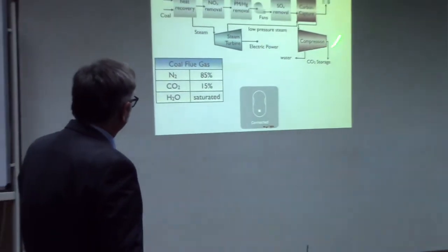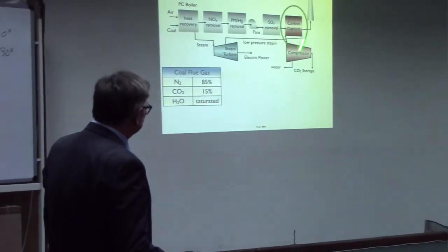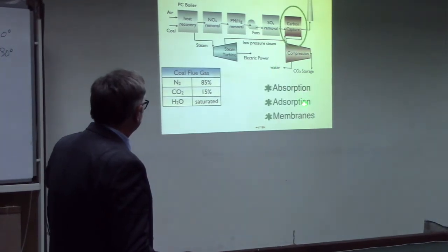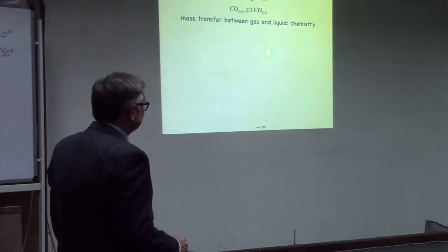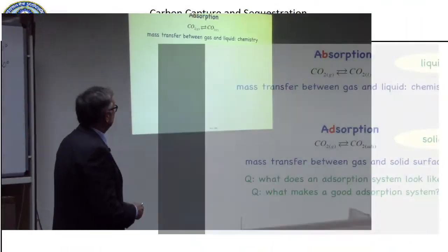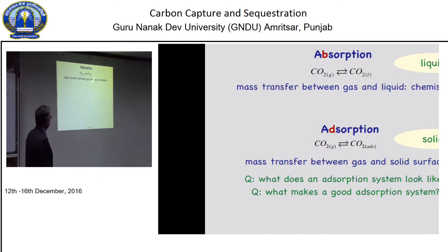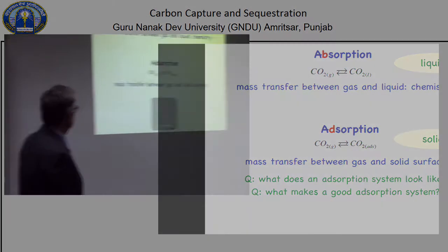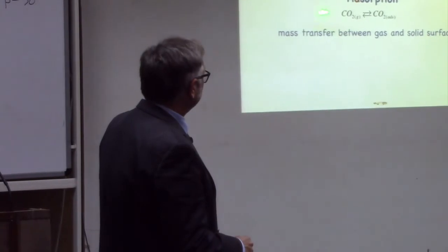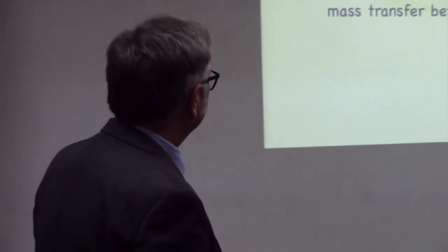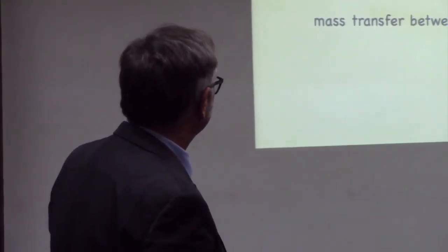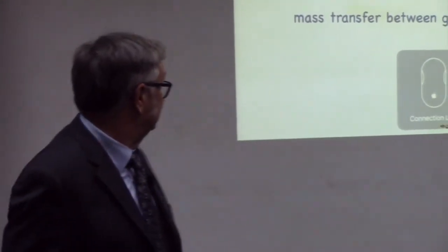Are you guys ready? Okay, so let's turn and talk about adsorption now. Again, we're focusing on post-combustion capture. And we're now going to look at the adsorption process. This is different. The absorption was talking about mass transfer between a gas and a liquid and the chemistry associated with designing solvents. In adsorption, we're talking about mass transfer between a gas and a solid surface. And that's a critical difference, and it changes virtually everything about these particular processes.